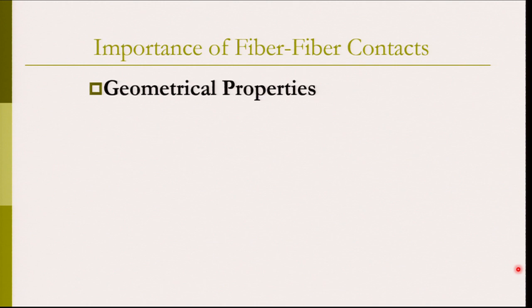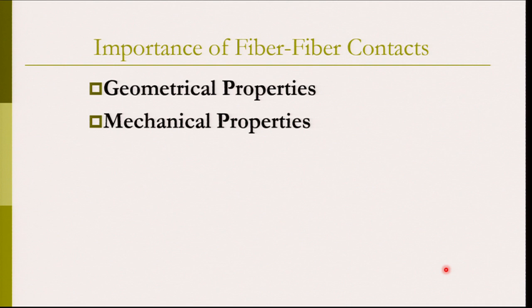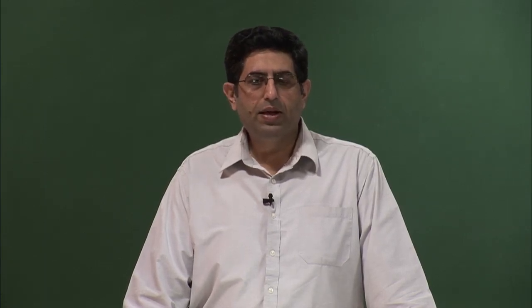Similarly, you have mechanical properties, for example tensile or compression. In case of mechanical properties, the fiber to fiber contacts play a significant role because fibers are the load bearing elements and the fiber to fiber contacts are the load transferring elements.